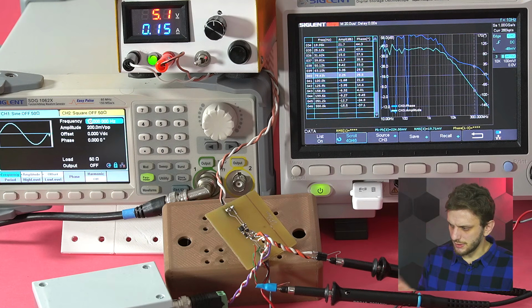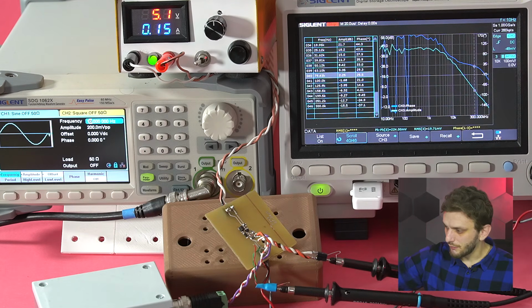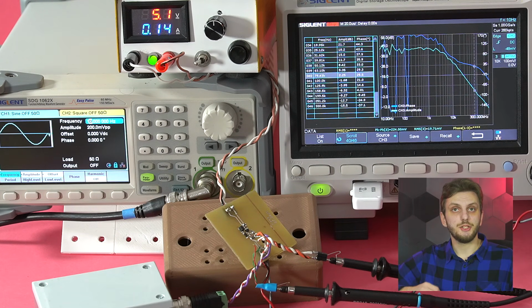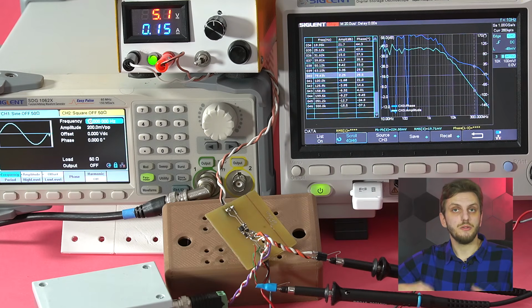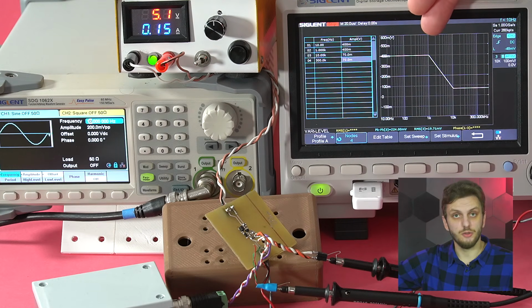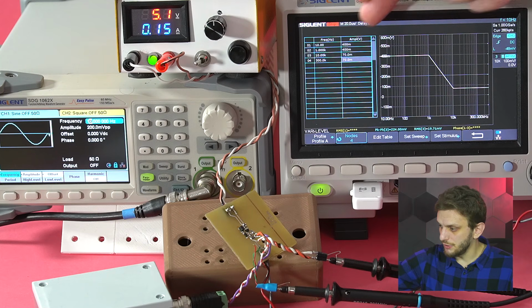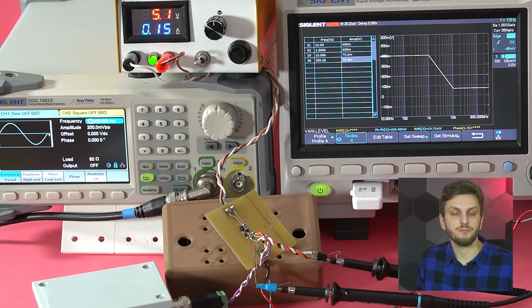But another thing that can be said about this measurement is that it's not very clean, so it's quite bumpy. And the reason for this is the injected signal. So I used a flat signal value for every single frequency. Now, some pieces of equipment will let you inject variable signal amplitudes. So one of the things that we can do is inject relatively large signals at low frequency, so go with 400 millivolts, and then drop down to relatively small signals at higher frequency. So this should prevent the injected signals from getting distorted, and it should help us get a cleaner result.